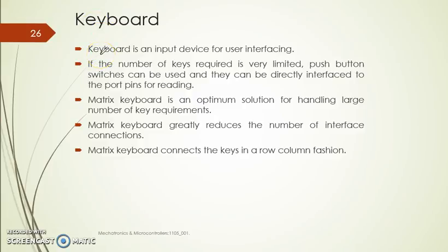We have learnt about switches, but whenever you have multiple inputs to be given, interfacing a single switch for every input is not a feasible solution. Therefore we go for a keyboard. Keyboard is an input device for user interfacing. If the number of keys is very limited, push button switches can be used, and they can be directly interfaced to the port pins for reading. Matrix keyboard is an optimum solution for handling a large number of keys. It reduces the number of interface connections.